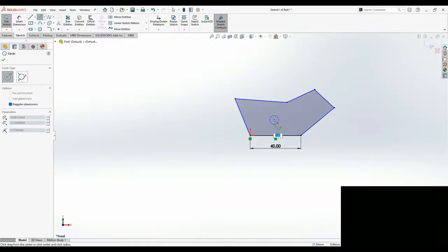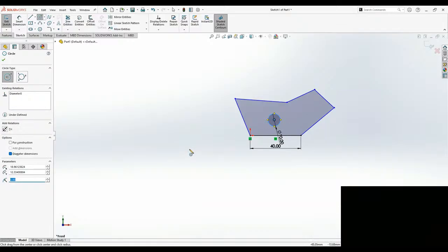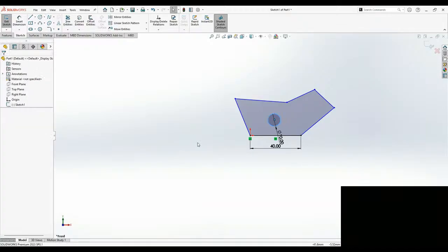Assume we'll have the length here. Okay, diameter 10 is fine. Well, this is what I'm having now. I'll simply press escape now. Now I would like to define all the geometrical constraints, okay, and even the dimensions. Before getting into the dimensional constraints, better you define all the geometrical constraints so that you can have the proper shape of your model. Let me show you.